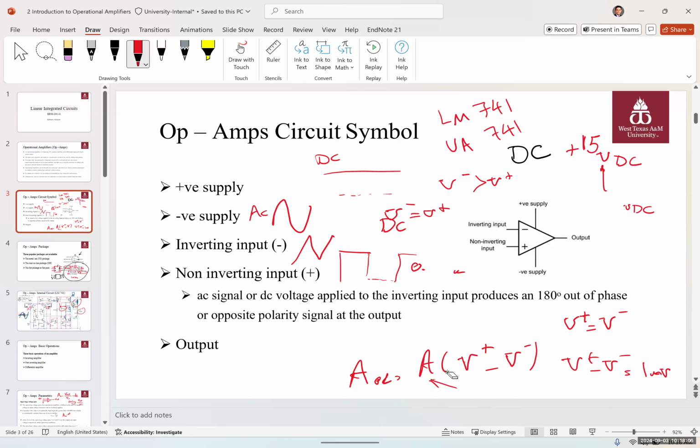And the way that it works, and the reason that it needs a timer, is that if it doesn't sense any motion for 2-3 minutes, it will automatically turn off the lights. Okay. That's the reason when I pass in front of it, it makes that click noise. It means it's resetting the timer. The timer is like 5 minutes or so, and then it's resetting it, so it's never letting it go down to 0 to turn off the lights.